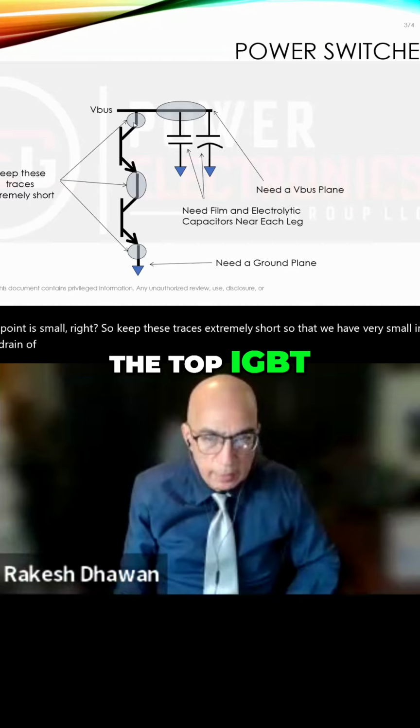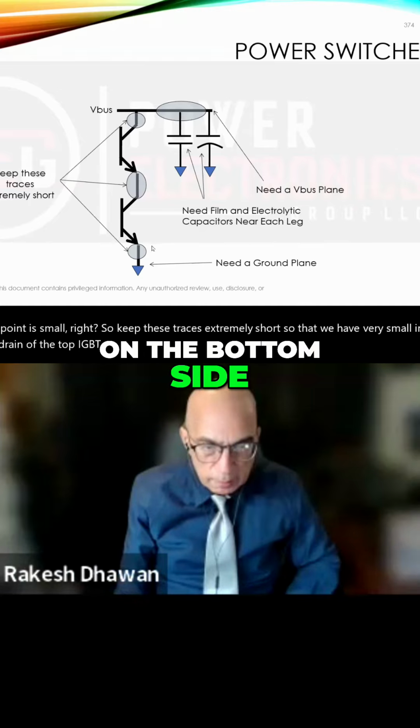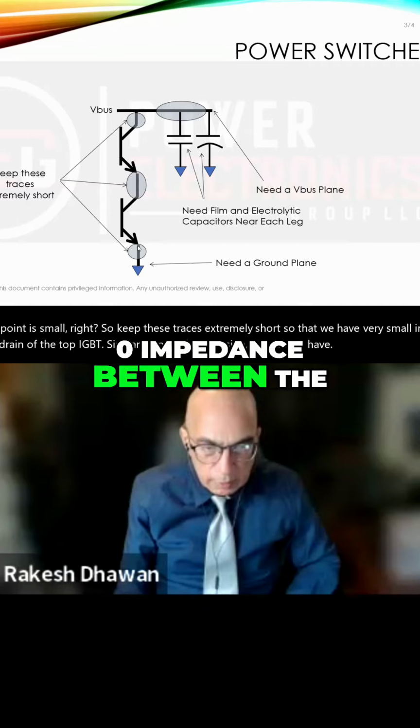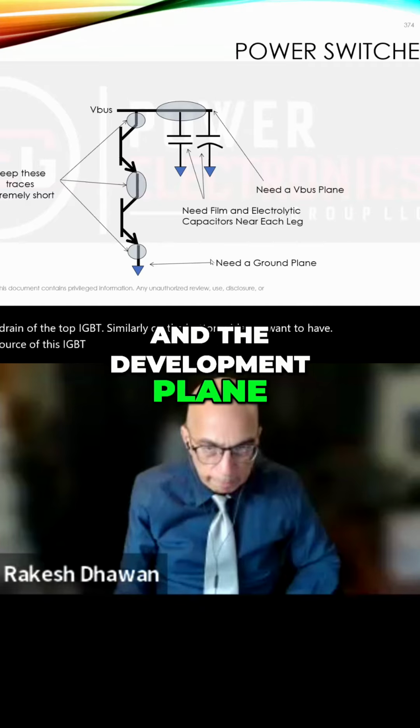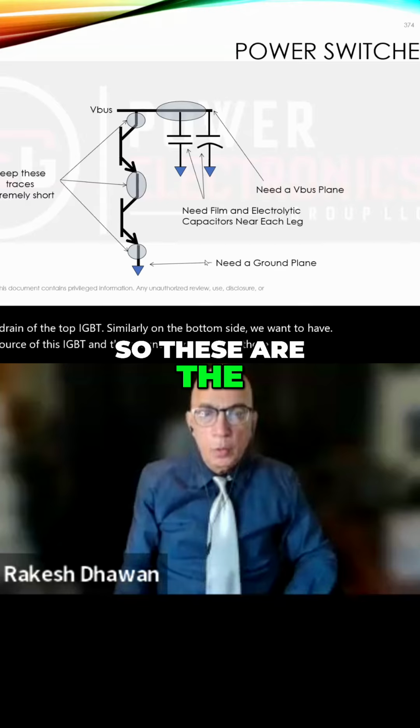Similarly, on the bottom side, we want to have zero impedance between the source of this IGBT and the ground plane, right? So these are the important rules.